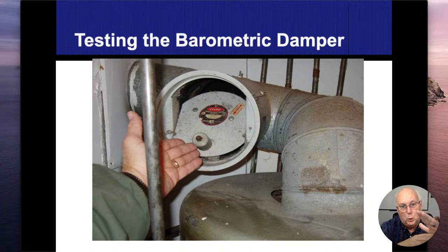And then this door gently opens and starts letting in 70-degree dilution air, and that mixes with the hot air that's going up and out, so that brings that temperature down. Now this thing's designed to find that happy place, so as it slows the venting down, it's going to get to a certain opening. Too fast, it opens more. Too slow, it closes, until finally it gets at a happy point.